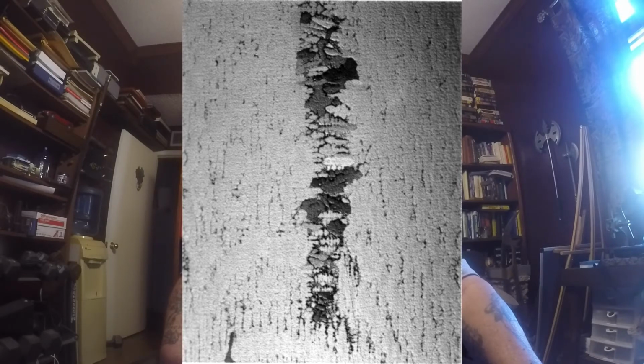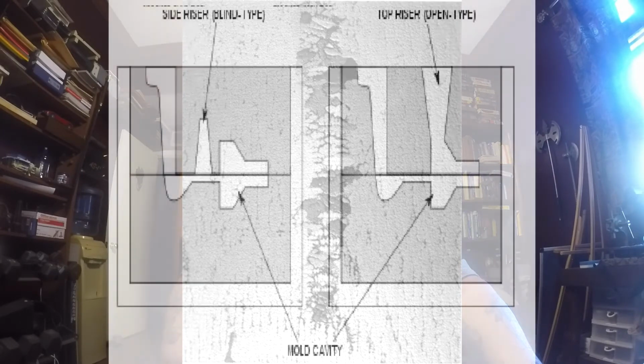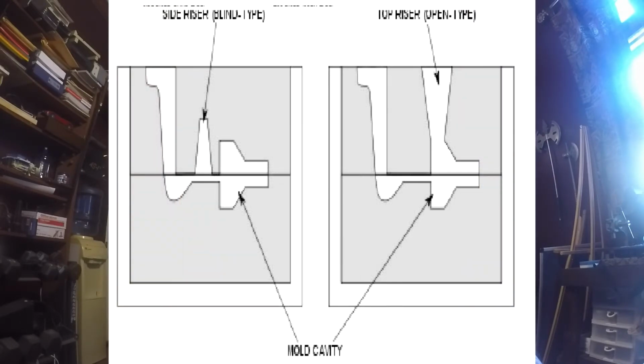If it's going to be pressurized, put risers somewhere in there, and gate into the risers, so the risers will have the hottest metal when you're done pouring, so that you won't have any of these gaps, even in uniformly thick casting walls. This next picture shows two of the three main riser types that you'll see if you ever use any.